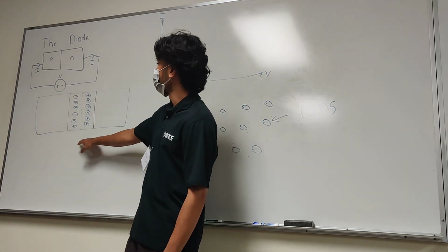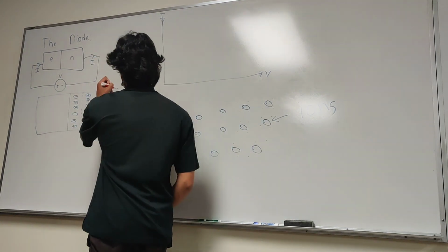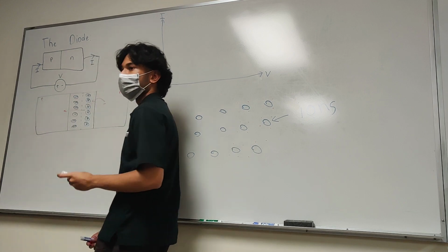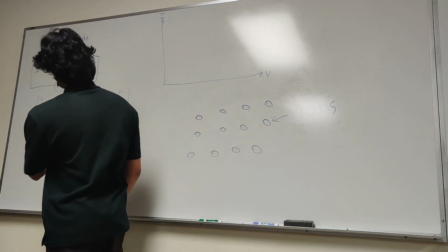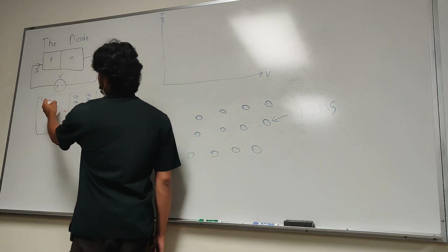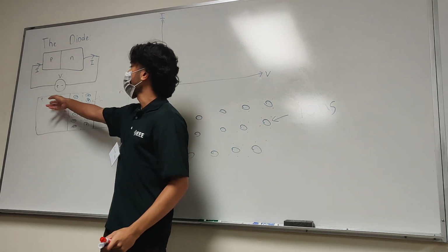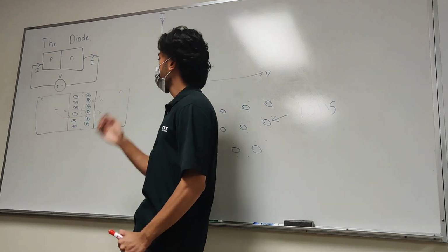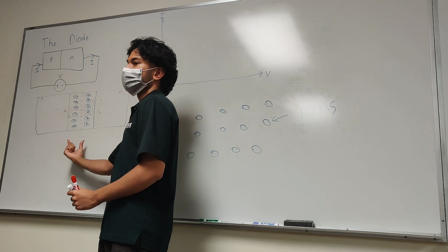Now, let's say we apply a voltage to this. Ideally, well, I'll backtrack. This is our N type, so P. So electrons over here will go into this region, get pushed across, right? This is a normal electric field, it's opposite, so, yeah. The electrons here are just going to get sucked this way and then holes are going to go this way, sorry. This is a hole, it's going to get pushed across, and electrons here enter here and get pushed this way, okay? So what we see is that minority carriers in our p-type get pushed across over here. Minority carriers in our n-type, our holes, get pushed across. This is very useful because we now have a way of separating charge based on what voltage we apply. Now, how this region changes with voltage is what we're going to explore next.